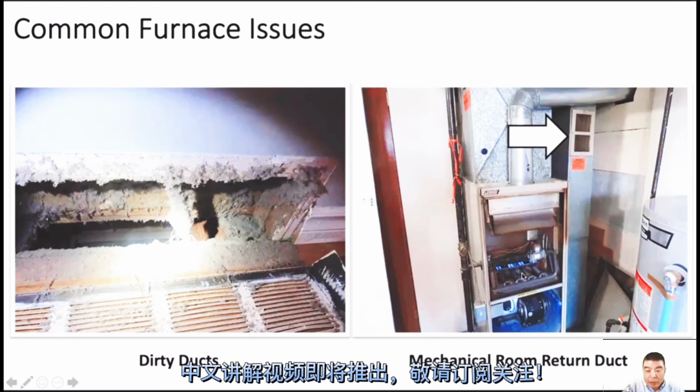If there's a standing pilot, that means it's low efficiency. Efficiency is less than 83%. With a high efficiency furnace, we don't have the pilot. Just like we said before, it's an igniter, a hot surface igniter or spark igniter, so we'll save some energy. I'll make a quick note there, Sam.